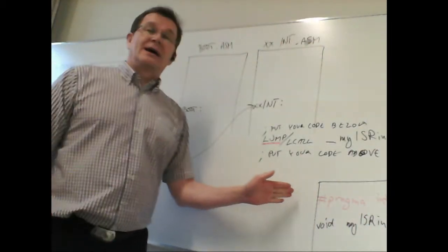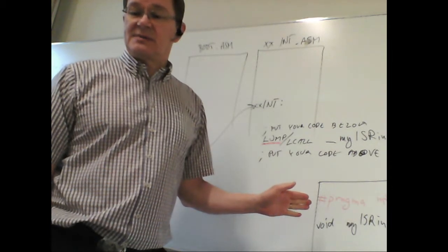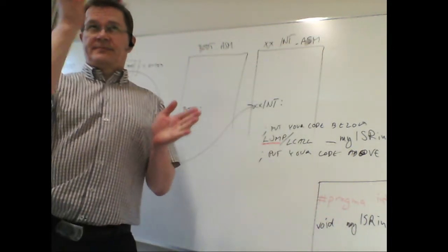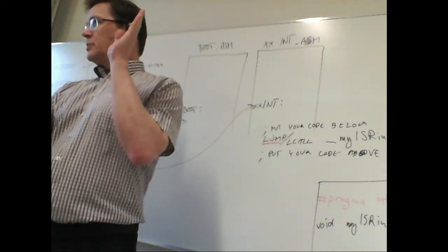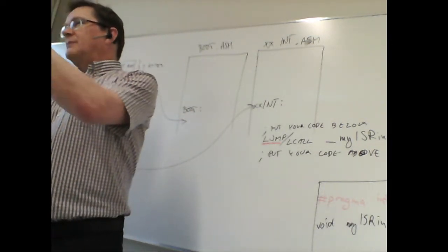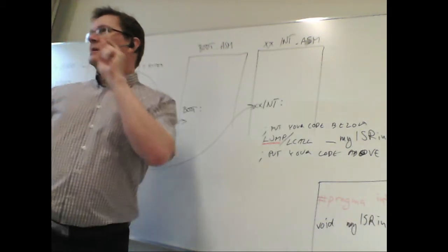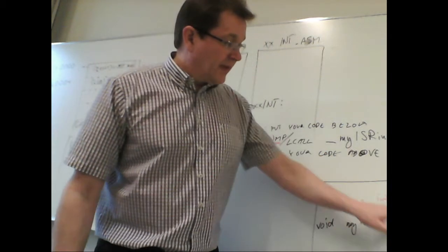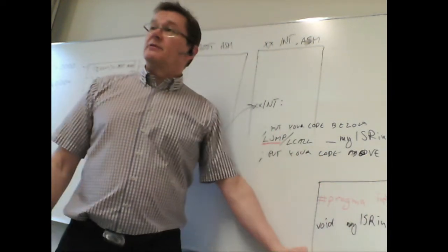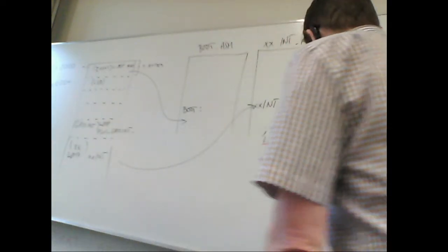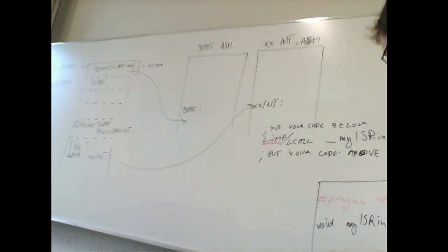So in the same way that in this GPIOINT.h file there's that definition of those IO ports as pragma statements, pragma IO port, that mnemonic, and which address, the same way here we can say pragma interrupt handler and the name of that function. Then instead of return, this actually returns from interrupt.